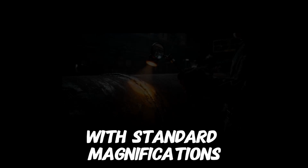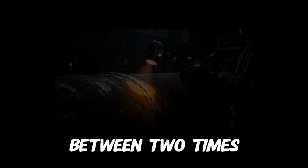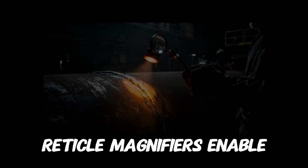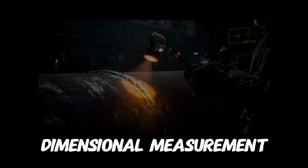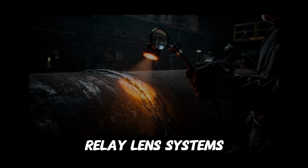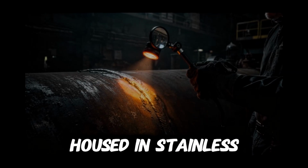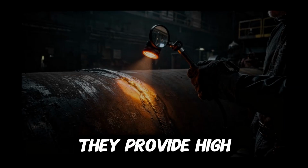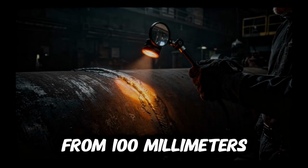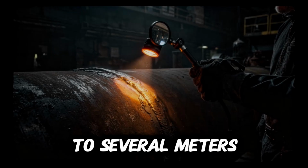Magnifiers utilize achromatic lenses to reduce chromatic aberration, with standard magnifications between 2 times and 10 times. For precision work, calibrated reticle magnifiers enable dimensional measurement directly in the optical path. Borescopes consist of rigid relay lens systems housed in stainless steel tubes. They provide high-resolution, undistorted images with working lengths from 100 millimeters to several meters.